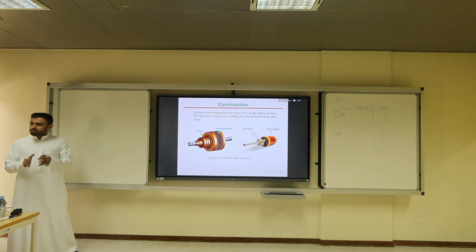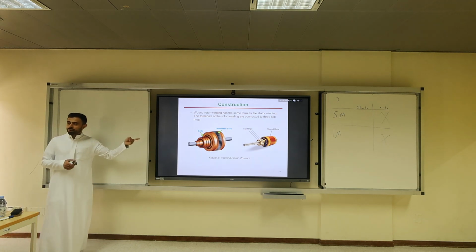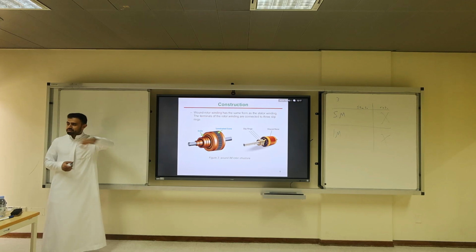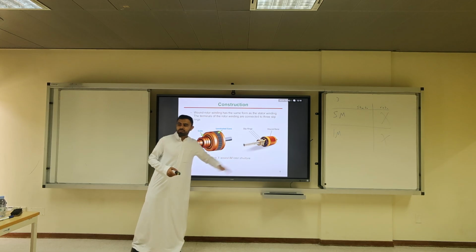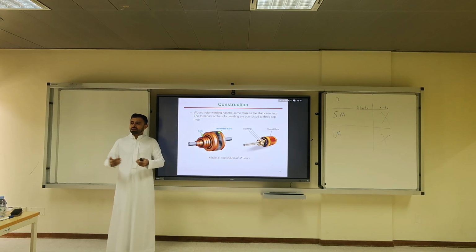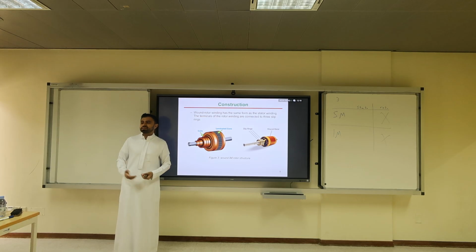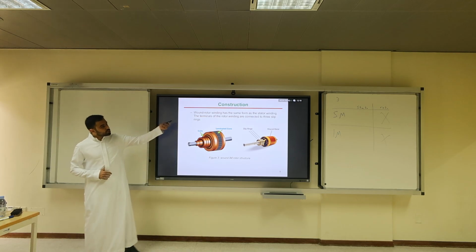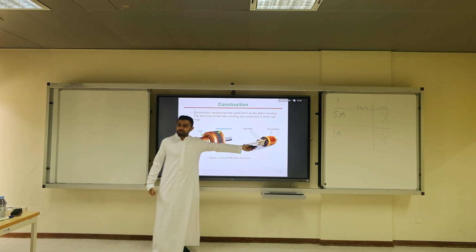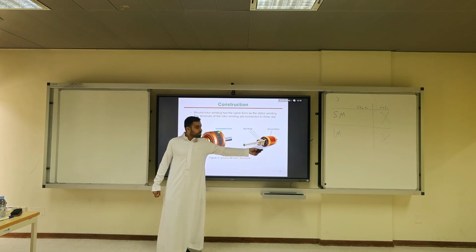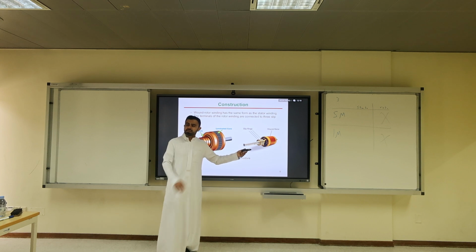No. The rotor of the synchronous machine has windings, while the rotor for the squirrel cage does not have windings. It's just bars. There are no slots, it's just bars. While for the synchronous, there has to be a current flowing by design. But the wound rotor also has windings. So there is induction with windings. But there is control of slip rings that we connect with external resistance to control. This gives you better control at starting speeds.